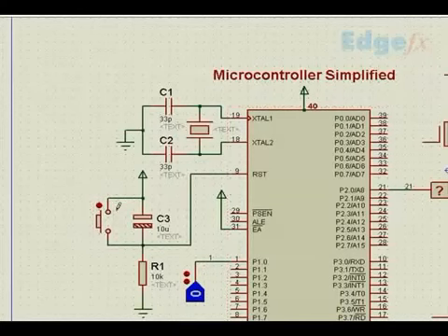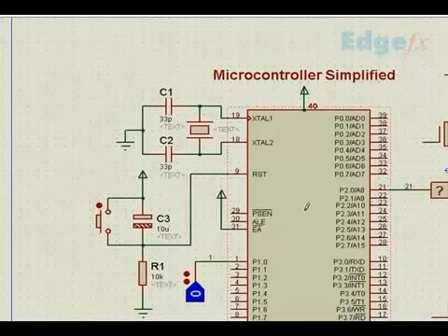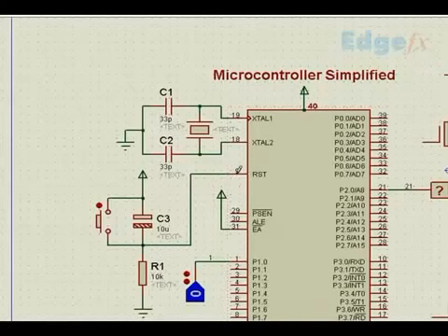Then we have also provided a push button switch here. In the event the user desires to start the program from the beginning, he can press it, but usually this is not required. Once you press it, the same thing happens again. The capacitor gets discharged and then it starts charging. This point goes to high and then goes to low. So this point is immediately made high once and then low, so that the program starts from the beginning.